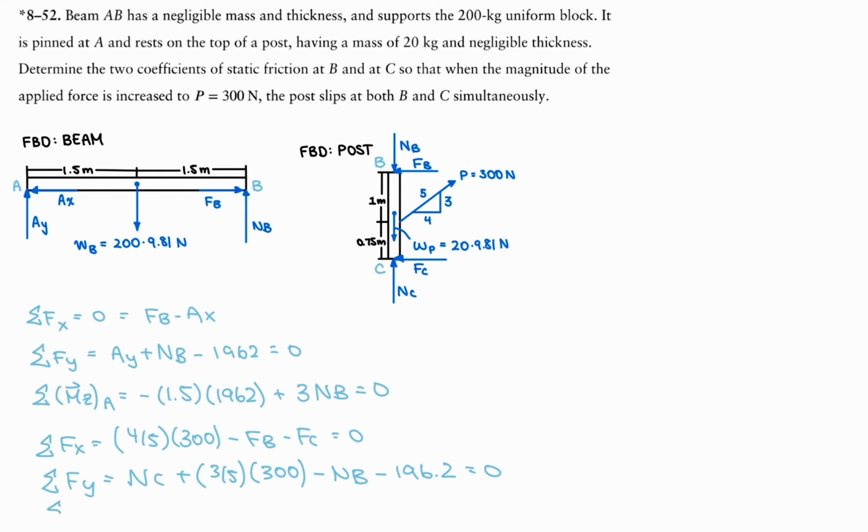And the moments, I'm going to take the moment at point C here. That's going to be 1.75 times force B minus 4/5 times 300 times the distance.